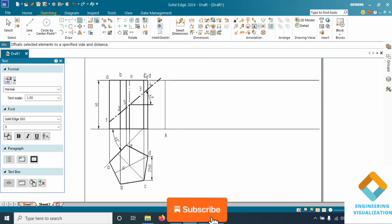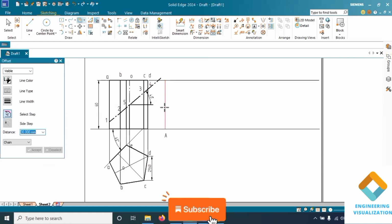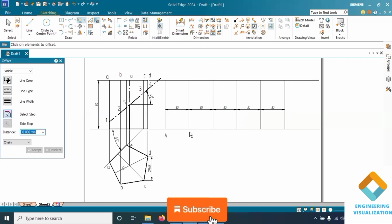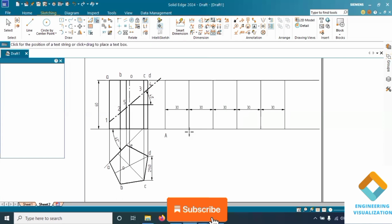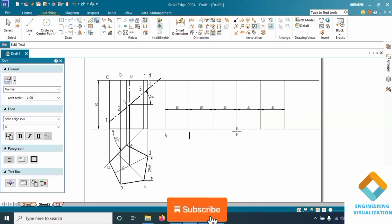Go to the offset command and select this particular line, and then offset at a distance of 30 mm. Give the distance 30 and click on accept. 5 lines we need to draw, 5 faces. Now wherever we got the cut points, from there we need to draw the horizontal lines, from 1. Give the naming here in capital B, capital C, capital D, and A.